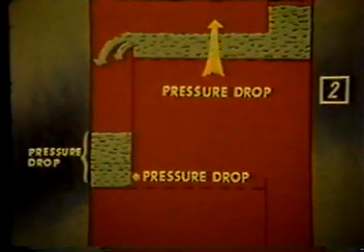The height of the frothy liquid is a function of the height and frothiness of the liquid in the downcomer. The clear liquid backed up in the downcomer is caused by three factors. One, the clear liquid height at the inlet edge of the tray. This is a function of the weir height and the liquid rate. Two, the total tray pressure drop.